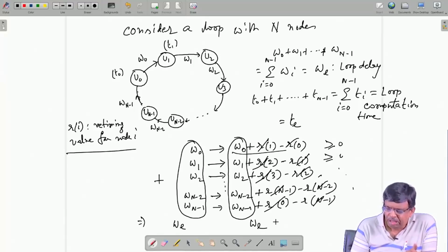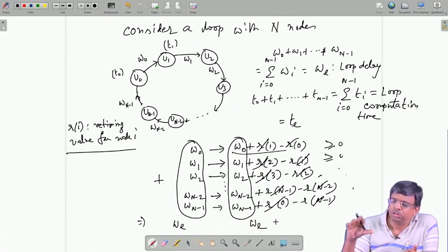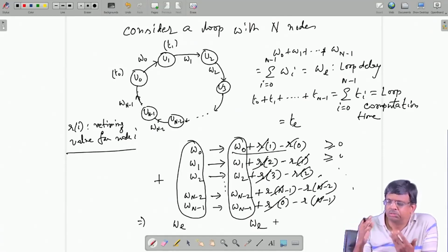In communication, there is something called a decision feedback equalizer, where the output decision about what symbol was transmitted is estimated and then fed back to the equalizer for refining the estimate. There is some structure, so there is a loop again. Loops occur frequently, and I always tell you, loops are the main cause of problems.